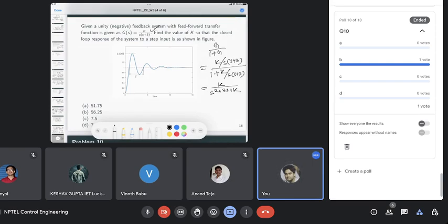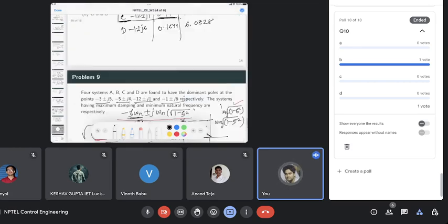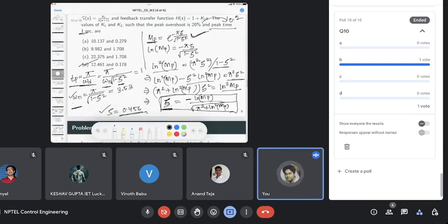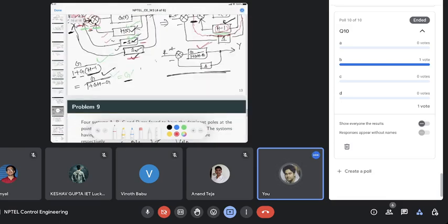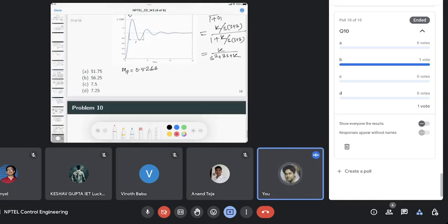Okay, so from maximum overshoot, what is this maximum overshoot here? I'll write Mp equal to 0.5266. From this maximum overshoot I have already written the formula for damping ratio, right? You can find the damping ratio from this maximum overshoot using that formula. So let's just calculate this damping ratio. So I'm calculating it to be minus logarithm of this value, this overshoot given 0.5266, right,